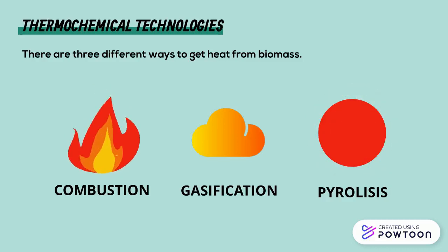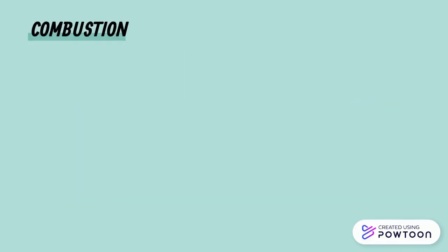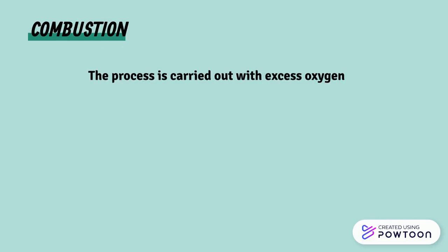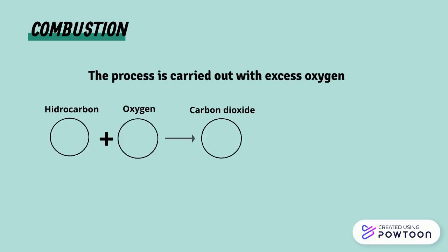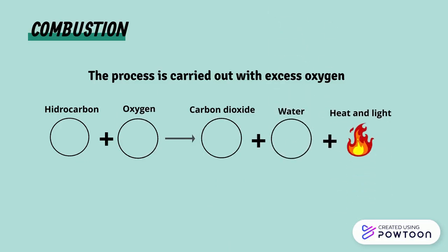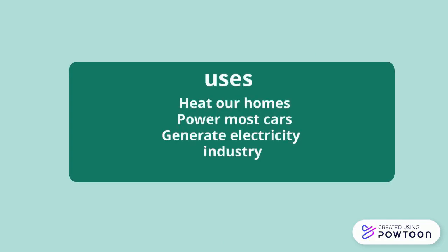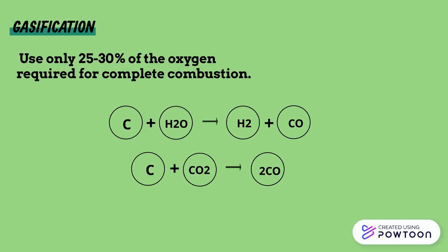The forced way is mainly done with three different methods like rotary dryers, flash dryers, and superheated steam dryers. The most common are rotary dryers because the size of the material is not important, but there is also a great risk of fire. On the other hand, for example, flash dryers are more compact and easier to control, but the material that we introduce must be small.